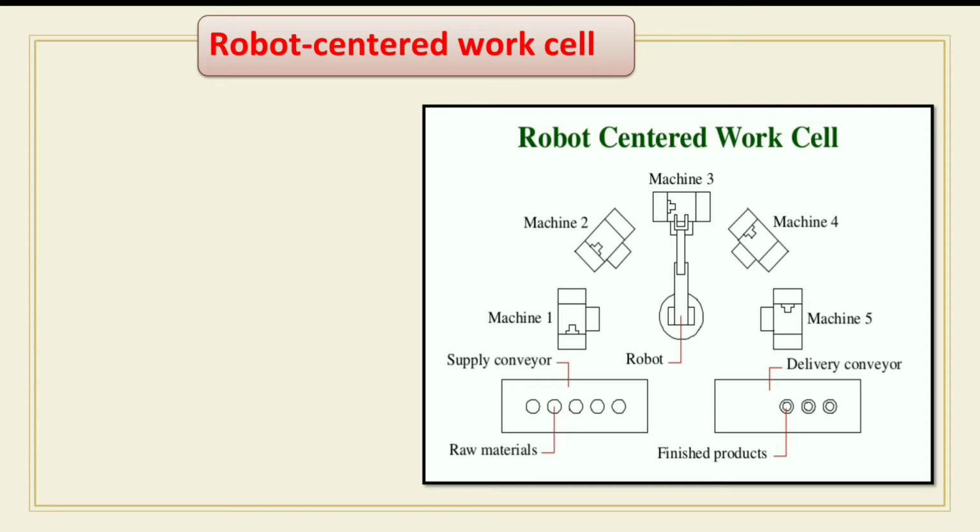In some applications, the cycle time of the machine is relatively long compared to the part handling time of the robot. Metal machining operations are an example of this imbalance condition. This requires the robot to be idle for a high proportion of the cycle, causing low utilization of the robot.